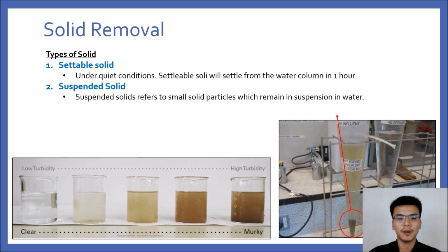So these solids will remain as fine particles that travel throughout the system. Drum filters and sand filters are usually able to remove the bulk of the suspended solids, but sometimes the suspended solids can be so fine that you require what we call a polishing method. And to polish the water, we utilize the foam fractionation method to polish out any fine particles. I will now show you the theory of operations of foam fractionation. The protein skimmer is the equipment that is used to achieve foam fractionation.